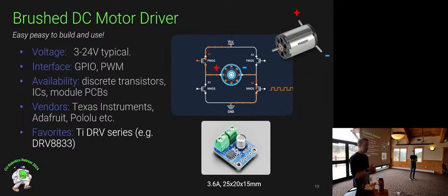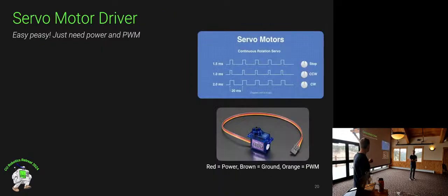So if you're running really fast, something like a propeller on a plane, you probably don't need a massive H bridge that can handle a lot of current. But if it's a Husky wheel, where you're going over boulders and there's a lot of torque, there's going to be a lot of current going through that motor, and you're going to need something that can handle it.